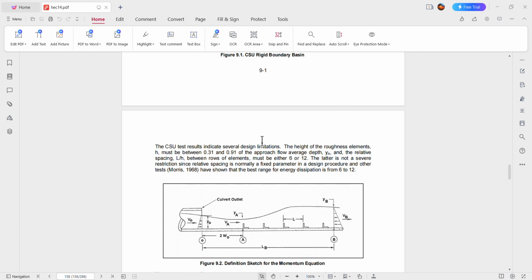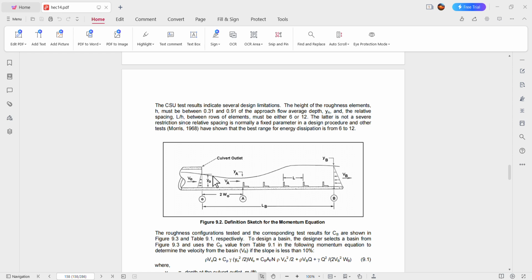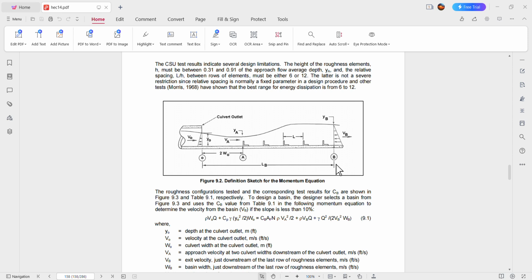This one is the section view. So what is coming over there, and this is the flow depth, will strike on this baffle wall, then again pass it, and the flow becomes higher and passes over just like this.